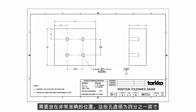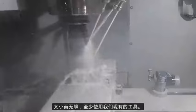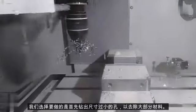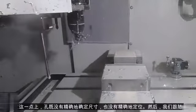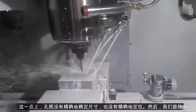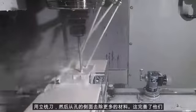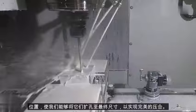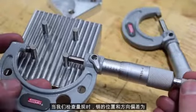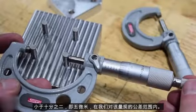At a 1/4 inch in diameter, these holes were too small for boring, at least with the tools we had on hand. What we chose to do is first drill the holes undersized to remove the majority of the material. At this point, the holes were neither accurately sized nor accurately located. Then we followed with an end mill and skimmed a bit more material off the sides of the holes. This refined their locations, allowing us to ream them to final size for a perfect press fit. When we inspected the gauge, the location and orientation deviations of the pins were less than 2/10 or 5 microns, which is within our tolerance for this gauge.